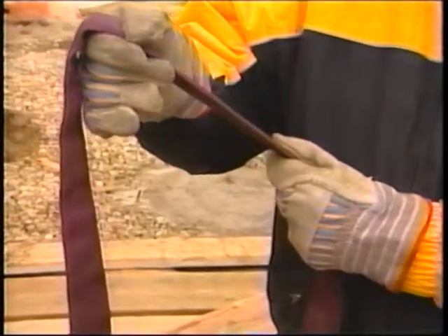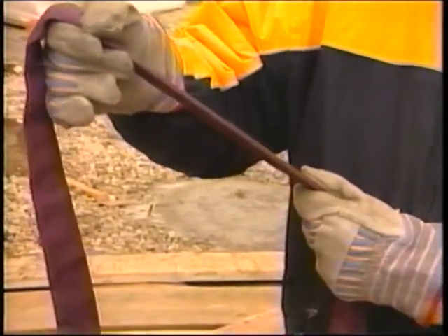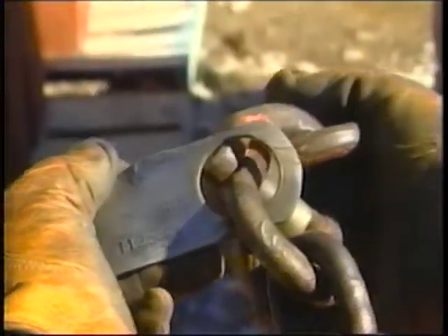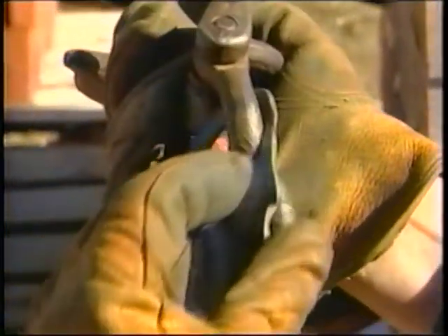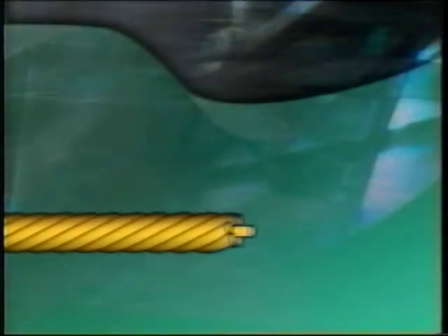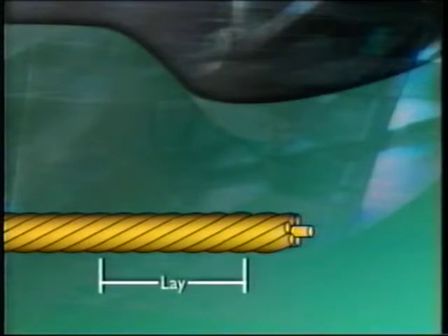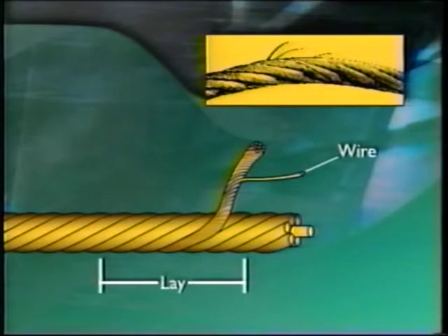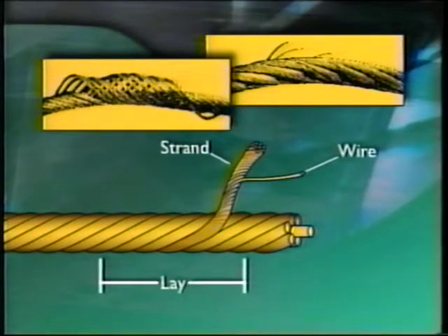Slings, fastenings, and attachments of handling and rigging equipment must be inspected for damage or defects each day before use. Alloy steel chains must have a permanent identification stating size, grade, rated capacity, and sling manufacturer. On wire rope slings, check the twists or lay of the sling. If 10 randomly distributed wires in one lay are broken, or 5 wires in one strand of a rope lay are damaged, the sling must not be used.